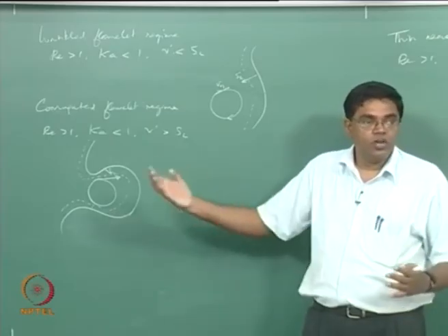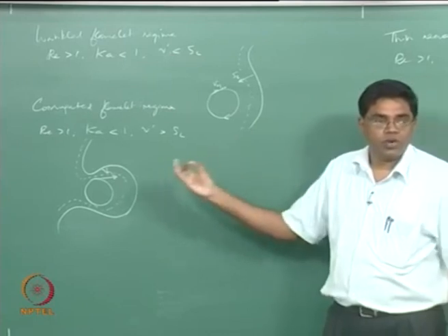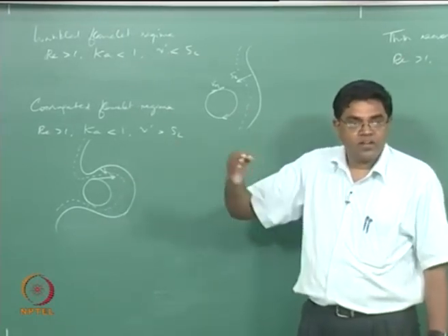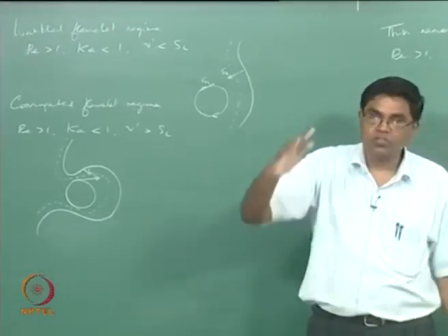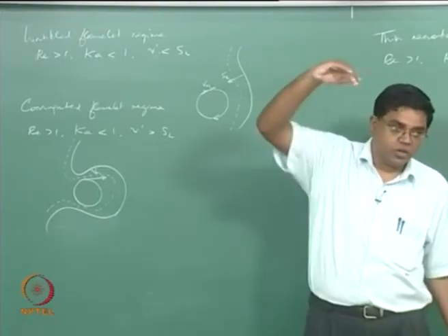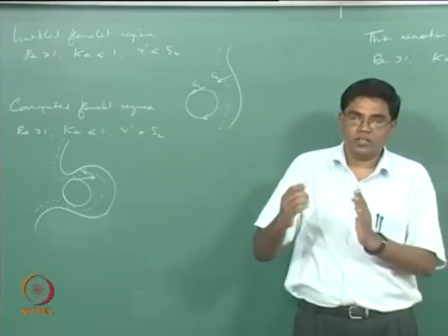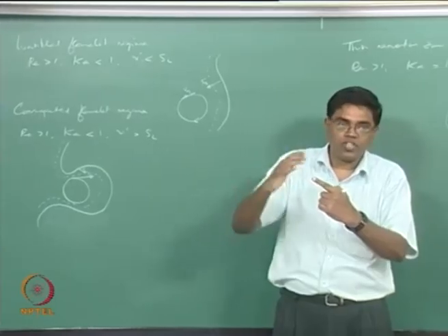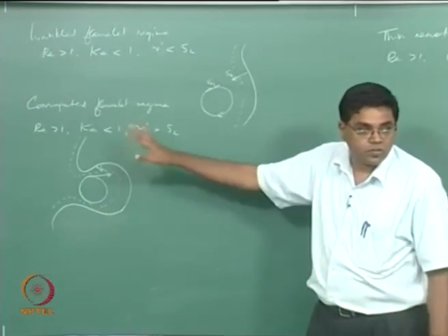So you can continue to preserve your idea because the original local structure of a one-dimensional laminar flame, how we extended it from a one-dimensional laminar premix flame to, let's say for example, a Bunsen burner, the shoulder of the flame there, or the base of the flame there, or the tip of the flame there, in all these things we try to accommodate the one-dimensional idea. Locally the flame is trying to match the flow, right, or it's shaping itself to match the flow, and that happens everywhere still, right.